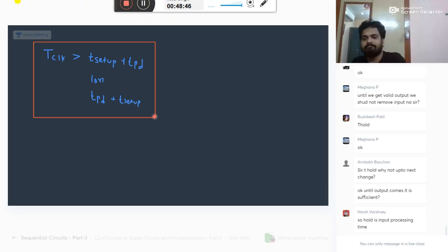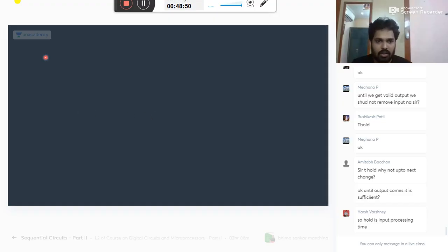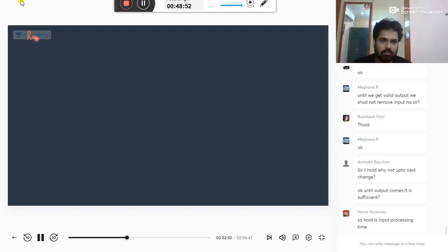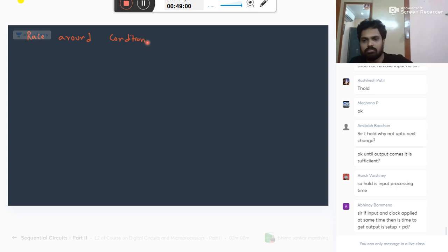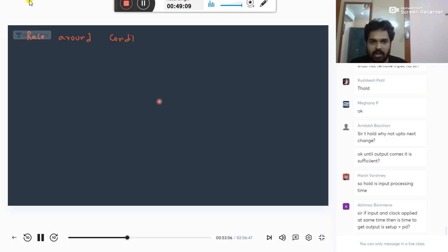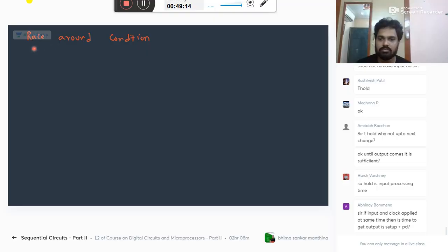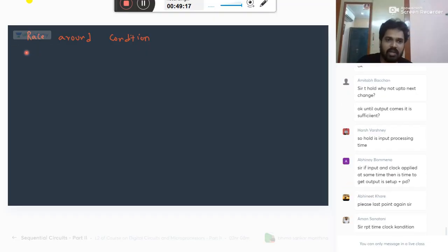Now listen here, one important condition: race around condition. If input and clock are applied, you should not apply them at the same time. You should apply the input earlier. Just wait for some time, forget about it for now. Now concentrate here. I will come back to that.